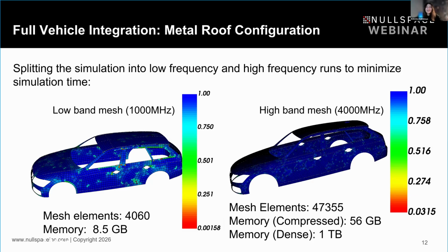And then you see, okay, here maybe I need to clean some surfaces, because many antenna engineers know this struggle: you import the CAD, which is not appropriate or good for electromagnetic simulations, and you need to clean it and then mesh it. So it's very good to see directly where you have these problematic areas.